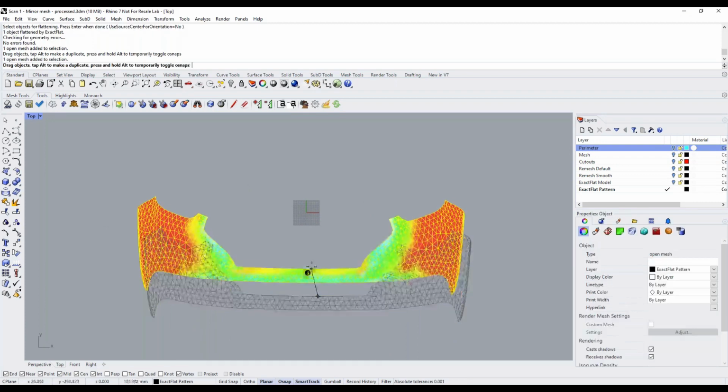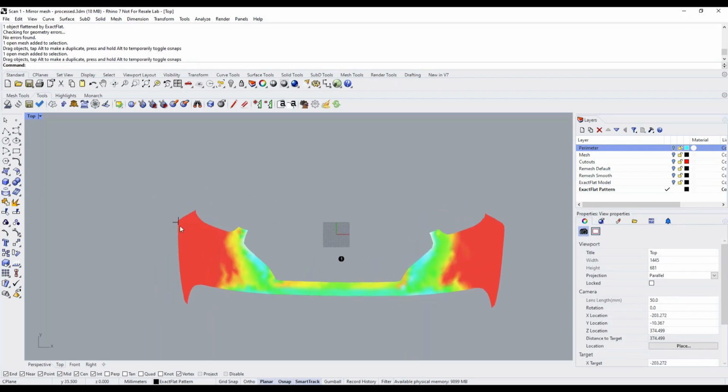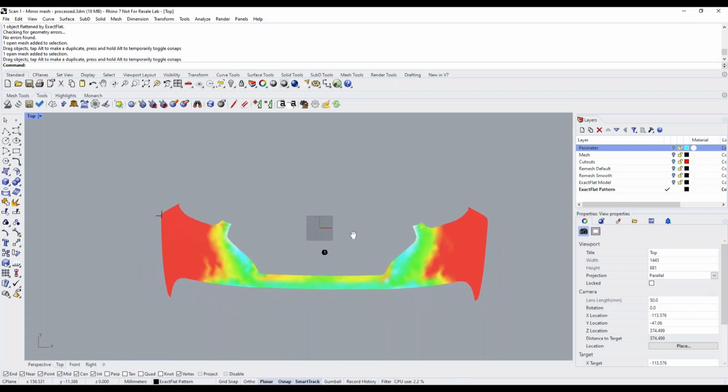We can see quite a bit of information just from this pattern. The color tells us roughly how much strain we have on the pattern. And as we look at the mesh, we can also see we have this cross mark here. We use color to represent the strain on the pattern piece, and that's probably the primary indicator of the quality and the accuracy. If our part was pure white, that would tell us that we don't have any strain. As we move through the spectrum, cyan represents up to 5% strain, green is up to 10%, yellow is 15%, and red is 20% or more.